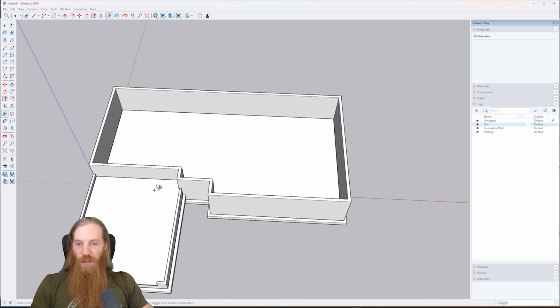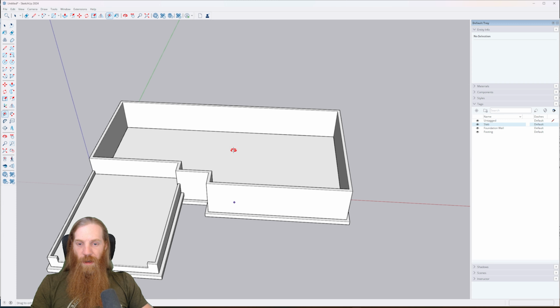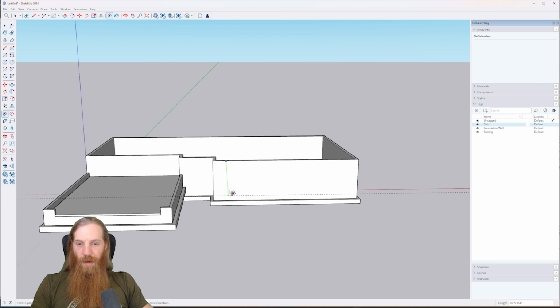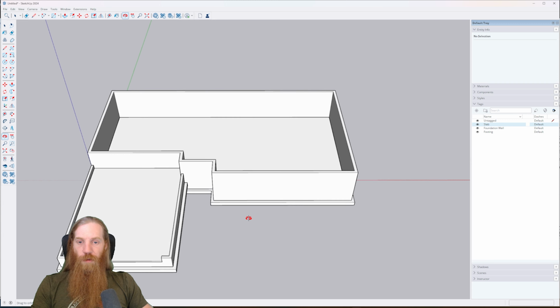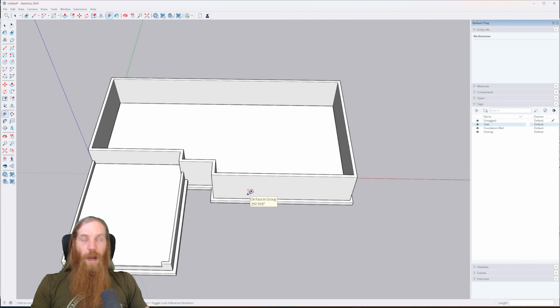So you're going to have times 3 for whatever the length of your total footing is, and then divide the height of your foundation wall by 16 to get the number of rows of rebar, and then multiply that by the total length of your foundation wall. When I'm adding up the total length of foundation wall, I'll add in an extra 4 feet at each corner for the overlaps. And then usually, if you have a long wall that's more than 20 feet, right?